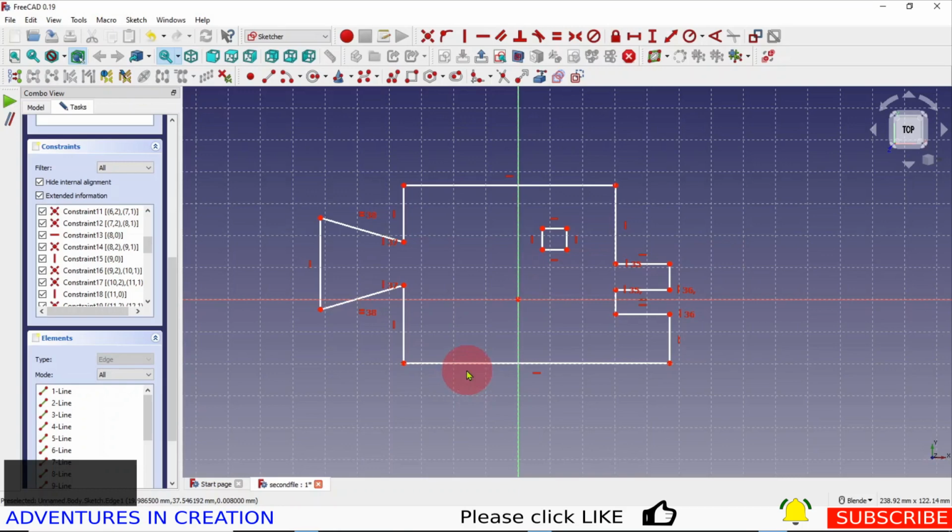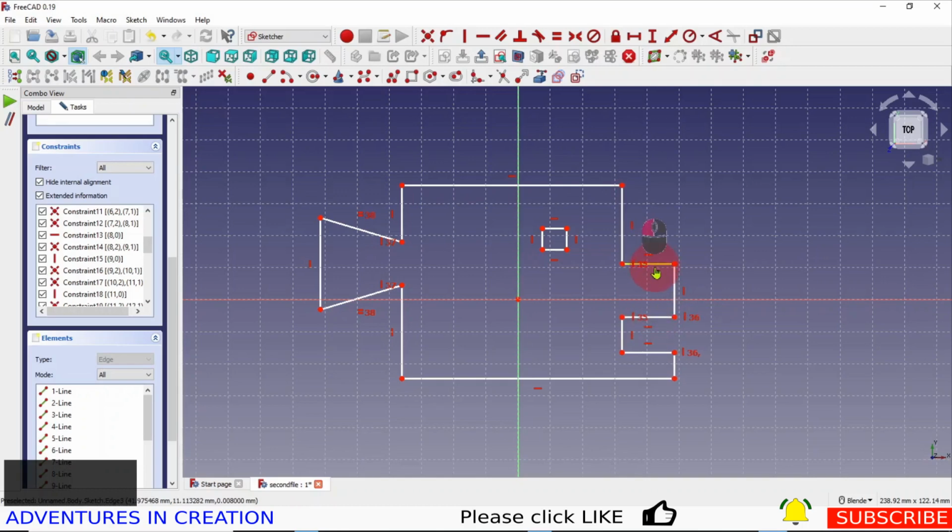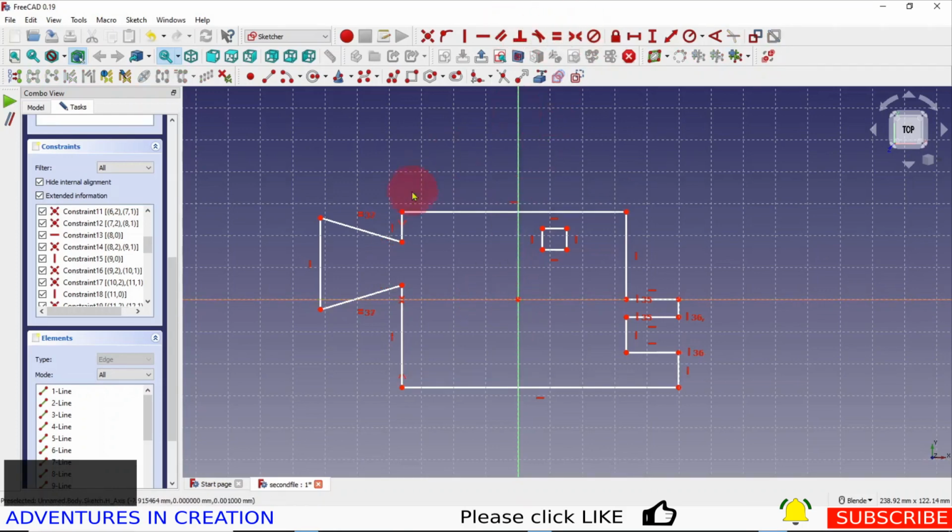So the best thing to do would be to pull down my geometry and get it roughly where I want it in terms of being symmetrical around those points. And then I can say this point and this point around this line are going to be symmetrical. Then I can say this point and this point around this line are going to be symmetrical.